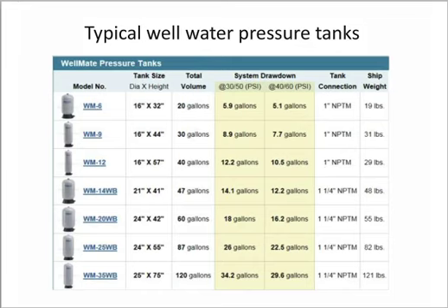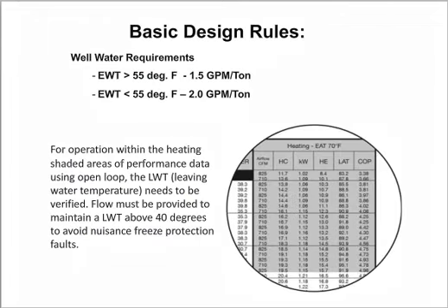Okay, how can I keep this well pump from turning on and off a great deal? So you want to get down to a point where it'll turn on and then run, and not keep cycling on and off. So often you want to consider adding a few pressure tanks onto the system. 2 or 3 is not unusual. Again, remember that homeowner has avoided the cost of a loop, so this is not a deal killer at all, because a ground loop is thousands and thousands of dollars, and well, pressure tanks are $300-400 each, plus some installation labor. So again, it's a good application. Just make sure you go in, maximize that savings for that homeowner, and apply it correctly.